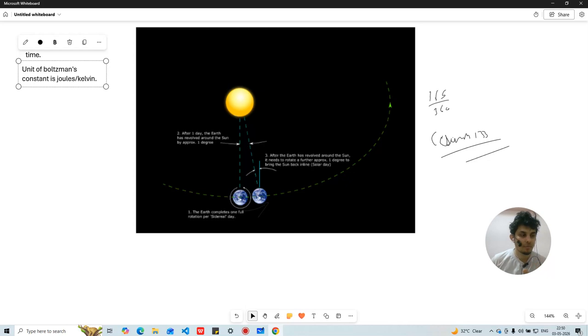Luminous flux per power, measured in lumens per watt. An incandescent bulb is 10 to 15 lumens per watt, a fluorescent bulb is 15 to 100, and an LED is 100 to 200 plus. Luminous efficacy depends on human eye sensitivity as well. Human eyes are more sensitive to green light, so not all watts of light are equally visible. This is described by the luminosity function.